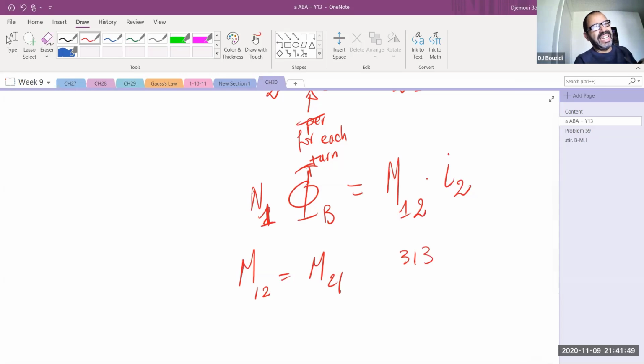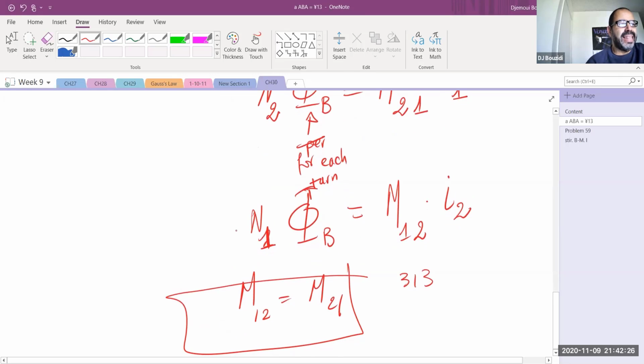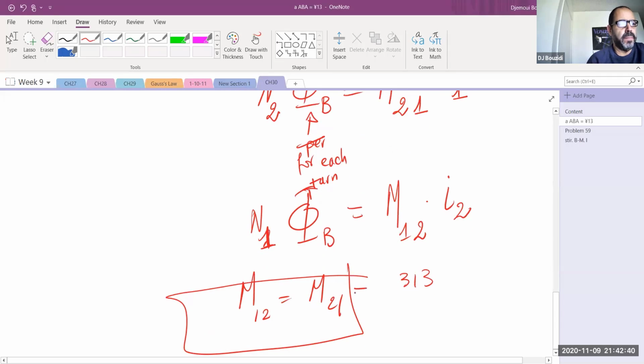The definition is related to the fact that you took those factors out. The only thing that relates then is the geometry of the two shapes. If this one overlaps with the other one through just this part of the area, that's why at the end the mutual inductance turns out to be the same. I would encourage you to look at it if you have time, especially if you're going into the mathematical physics part of it, where the integral is interesting to show that the two are the same. The book was vague on why N2 and N1 are needed, and they are needed because of how the mutual inductance is defined. It's not a choice why N2 and N1 are taken out. In this case the mutual inductance is the same, so I'm going to represent it by the letter M, period, end of story.